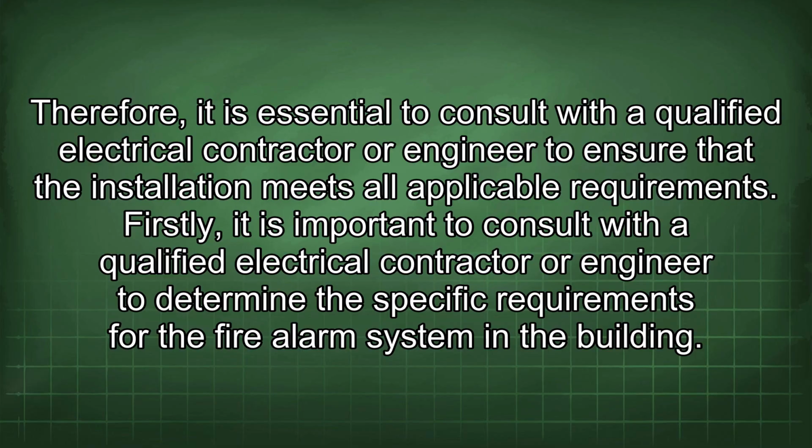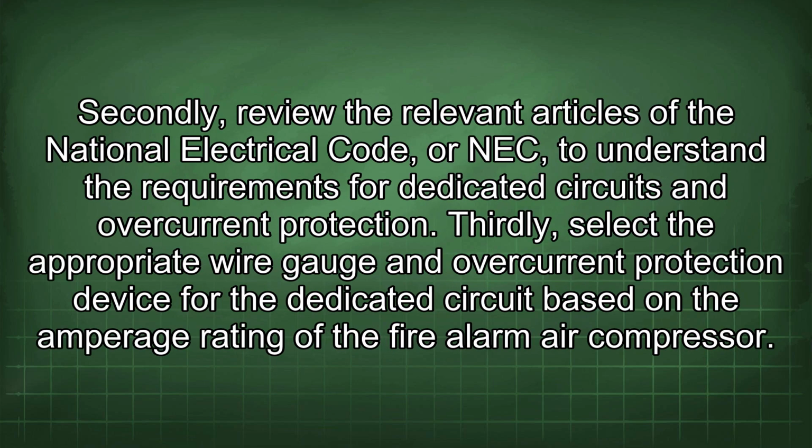Firstly, it is important to consult with a qualified electrical contractor or engineer to determine the specific requirements for the fire alarm system in the building. Secondly, review the relevant articles of the National Electrical Code, or NEC, to understand the requirements for dedicated circuits and overcurrent protection. Thirdly, select the appropriate wire gauge and overcurrent protection device for the dedicated circuit based on the amperage rating of the fire alarm air compressor.